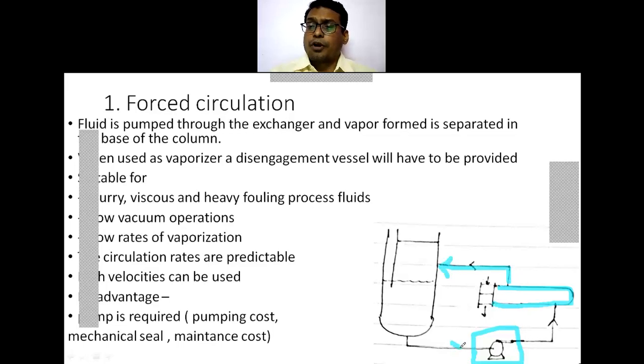So the bottom product is pumped into the heat exchanger. The fluid is pumped through the exchanger and the vapors formed are separated in the base of the column.